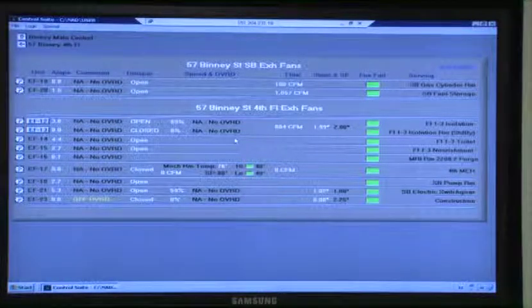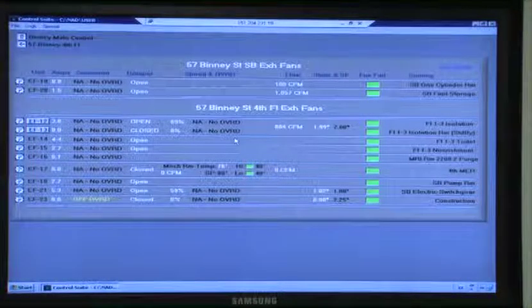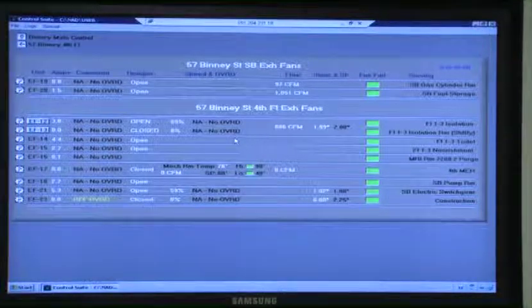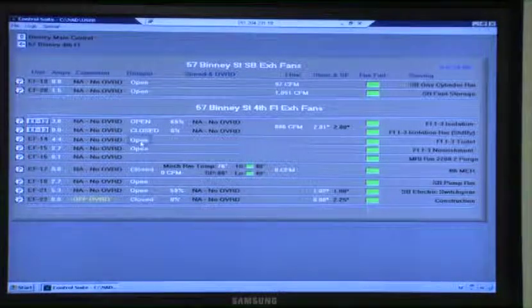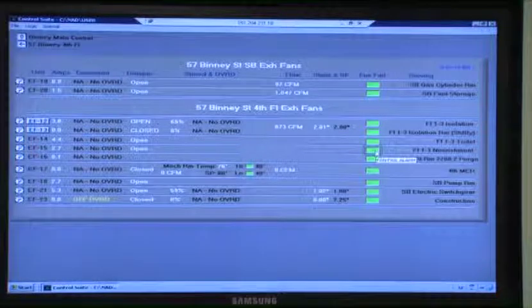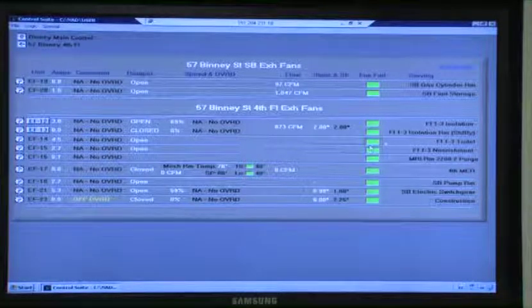Okay. One of the good things, if you always have questions about what it's doing and how it's doing it, is going back to those floor measuring stations and looking at the exhaust fan that was associated with it. Exhaust fan 15 was the 3rd floor that we just looked at. We knew it had flow at the 15th floor. So I know that damper's gotta be open, because it was on the 4th floor. And we know whether or not it failed. If there's something wrong with it, you can also go to the floor and see 0 flow, or a little bit of bypass. That's the whole premise behind it.